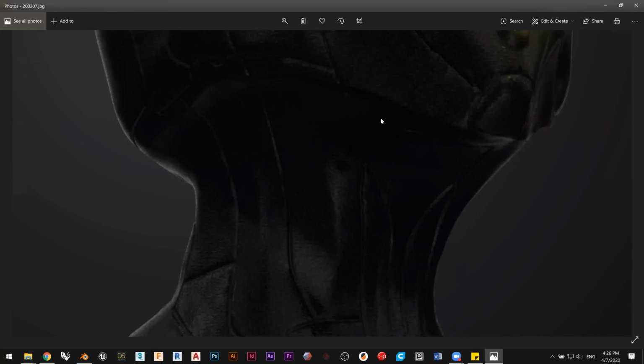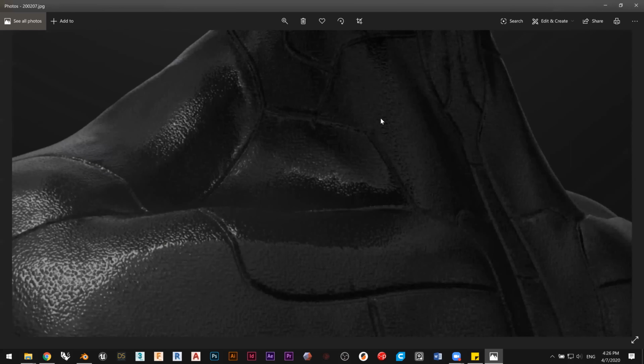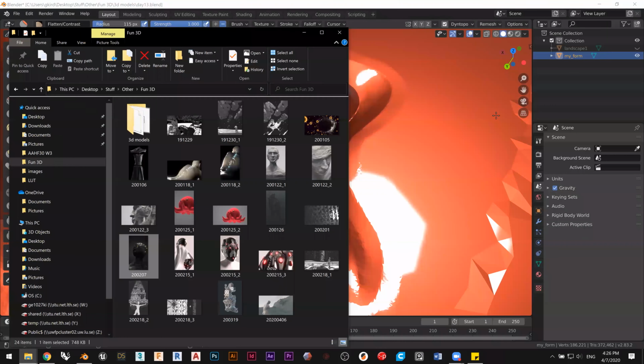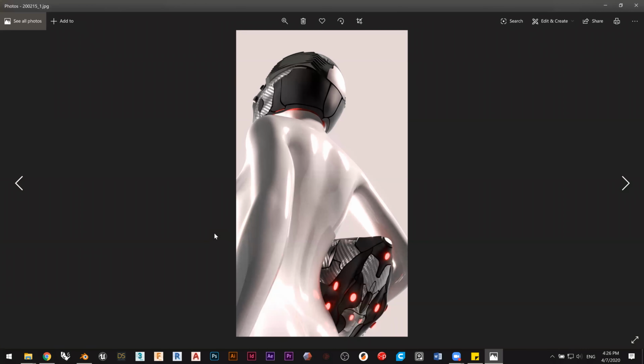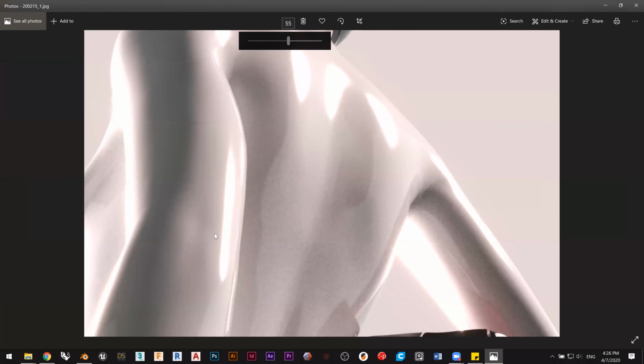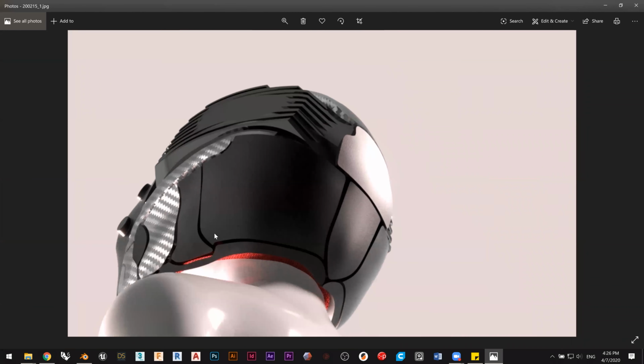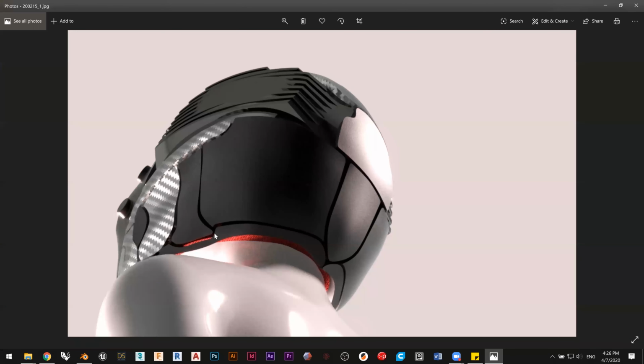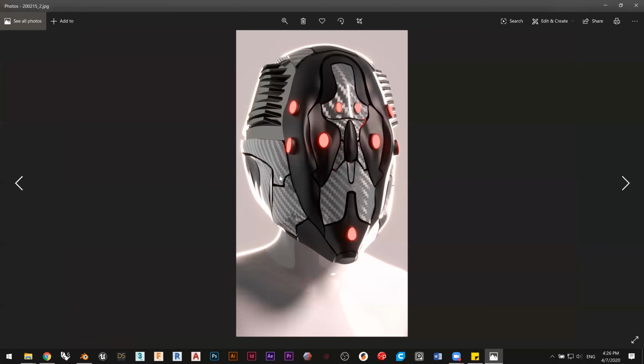It also has a texture attached to it, a noise texture that I've created. It's a closed mesh, but it's not a perfect mesh, simply because it's low resolution. But tomorrow, what I'm going to show you is how I rebuilt that helmet in Rhino from scratch. So you import the mesh into Rhino, and you rebuild all of the surfaces in Rhino, and then you have a NURBS polysurface model, right?